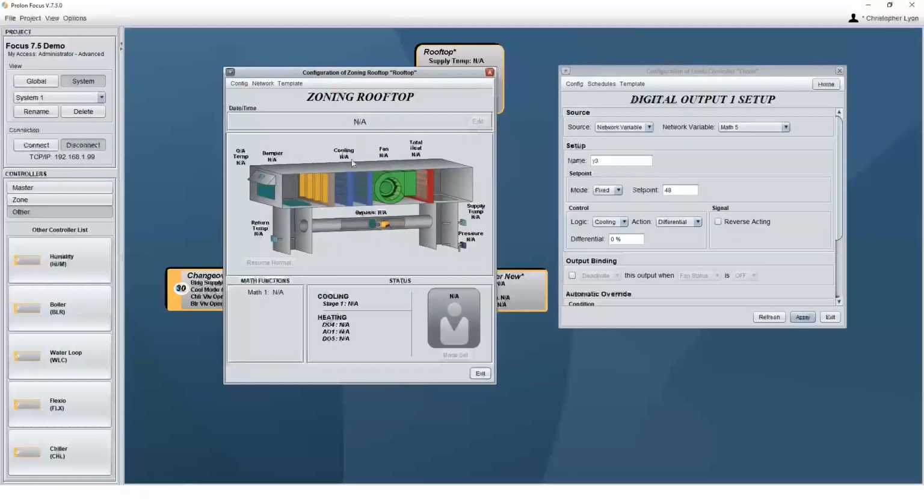The number that is represented above your cooling coils will be directly related to what is immediately being requested and allowed. So until I determine that it is safe and proper to turn on third stage cooling, this number will not change to 48. Technically, I could use any number between 32 and 48, and it would still work on this. But this just allows us to set that up real easy. I don't need a differential in there. Now we can continue on.